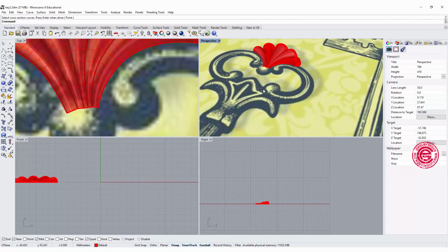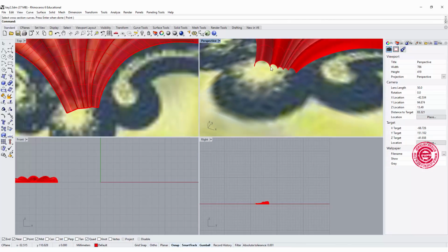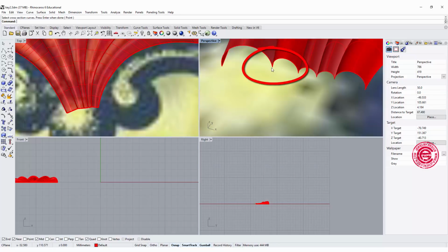This is a nice model, but one thing for metal casting is if you look at this profile, it's connected this way. That means there is almost no thickness where it's connected. That means when you are casting, it might cause an issue. So what I'd like to do now is change it just a little bit there.